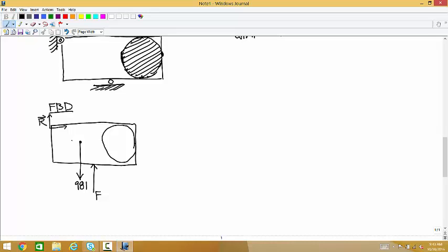One of them just isn't going to come into it at all. The y component isn't going to matter at all because if you put it at the right x location, you can give it any y location and that's just moving the force along its line of action. It doesn't change the problem.